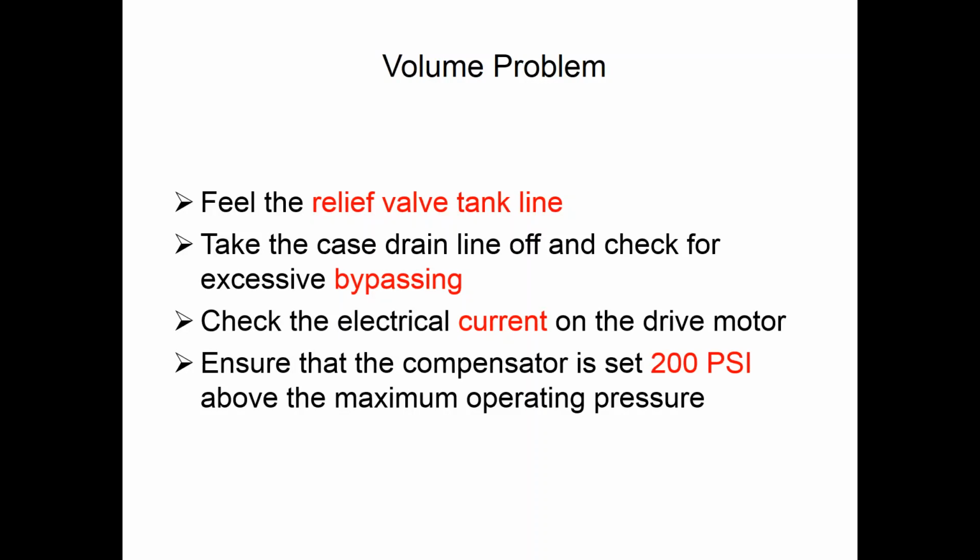Now, very seldom do I see anybody turning pressures down. Mostly I see people turning pressures up. But what I do see on occasion is that a pump gets installed and everybody's warned, do not touch that pump. Nobody does. Well, here's the thing about a spring setting. Springs can never gain tension. Springs can only lose tension. So the effective setting is going to drop. Make sure that it is set at least 200 psi above your maximum load pressure.